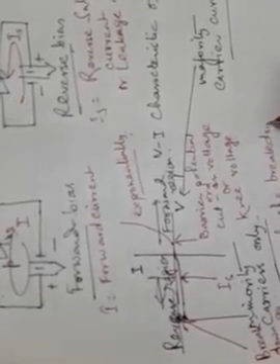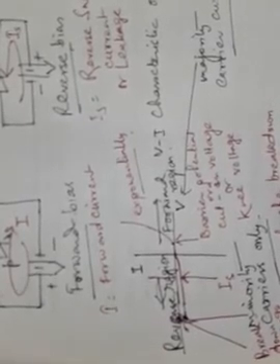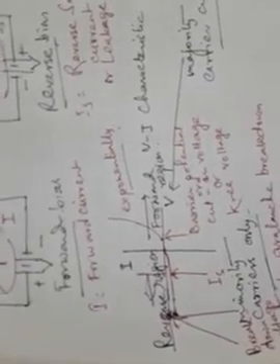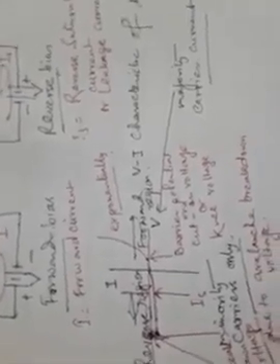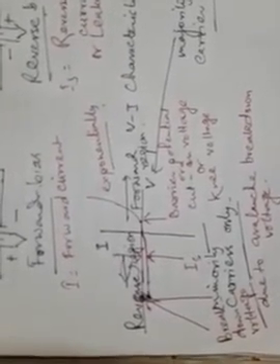And this avalanche breakdown voltage is specific for any particular diode. So you have to be careful about this breakdown voltage, and a diode working in reverse bias should be kept within this breakdown voltage so that the device does not get destroyed during its operation. So this is the VI characteristic, and because of it, the plot between V and I doesn't look like a straight line, and because of this the diode is called a non-linear device.